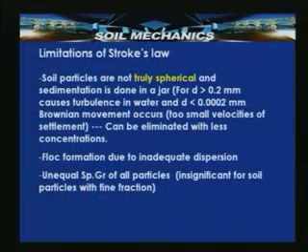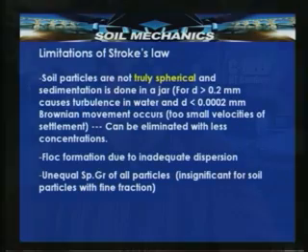There is also one more limitation: the possibility of flock formation. Due to inadequate dispersion, though we pre-treat the soil, flock formation may still exist. Also, it is assumed that the specific gravity of the soil particles is constant, so there may be an error because of the unequal specific gravity of all particles, which is insignificant for soil particles with fine fractions. To a great extent, these problems can be minimized to give realistic results of the fine fraction analysis.